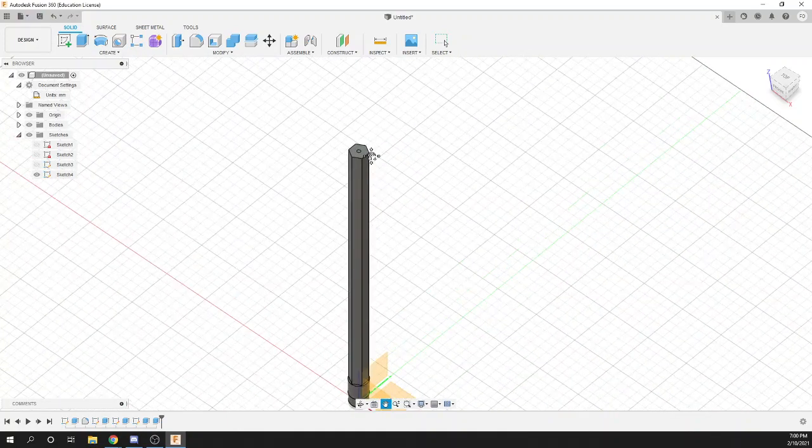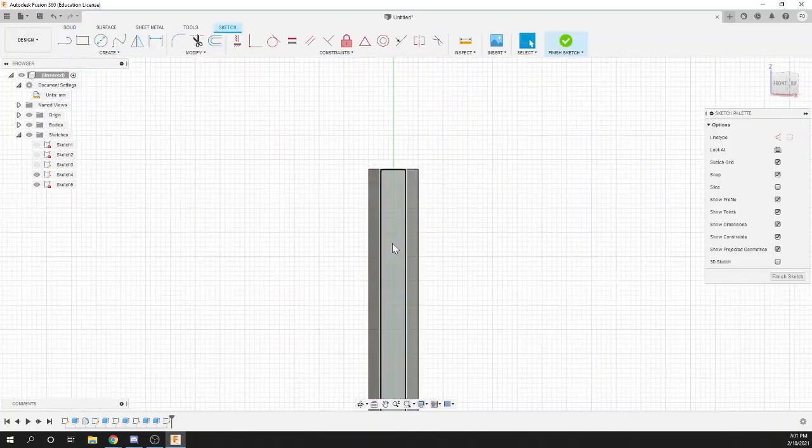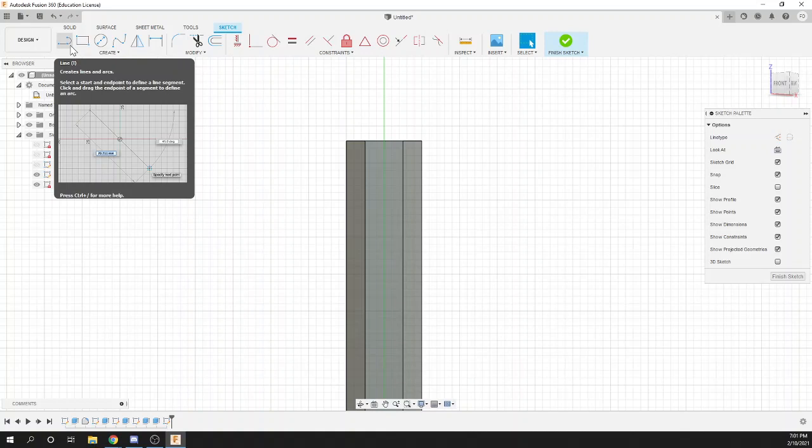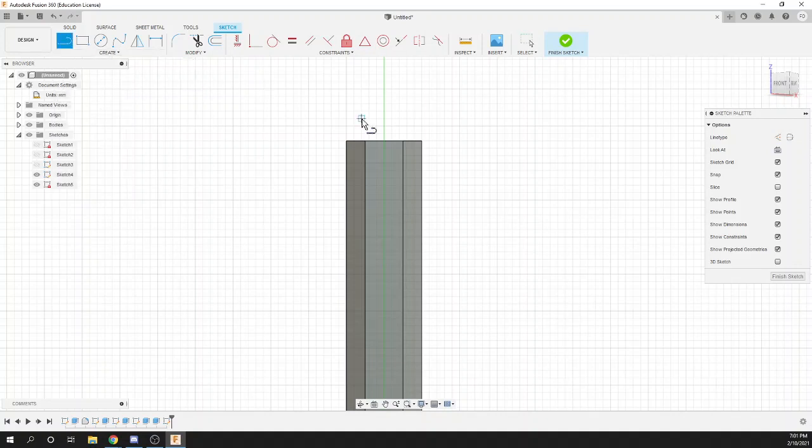And then what we can do is finally kind of sharpen our pencil. So what we're going to do for this is click this edge face. So any side of your hexagonal prism, I guess, we'll select that and create a sketch. And then what we're going to do is just create another profile that we're going to end up revolving. Essentially. And so that's another tool similar to Extrude that'll help you kind of manipulate a 2D sketch to have a 3-dimensional effect.